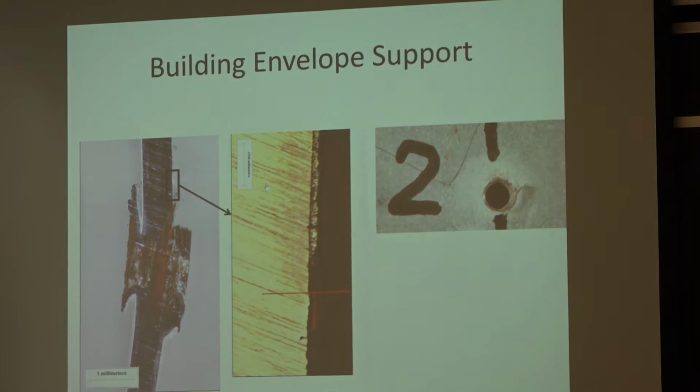So you have moisture on that surface. You can have some droplets sometimes, but you can't expect to reach galvanizing that is beyond that area of shared electrolyte. The electrolyte is only shared in the vicinity of the hole, so it doesn't matter that you have so much zinc further away, it's not going to protect you anymore.